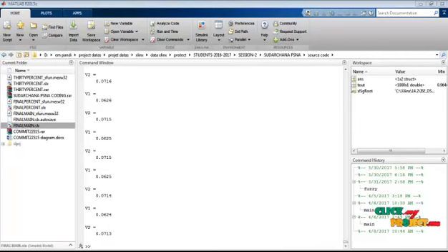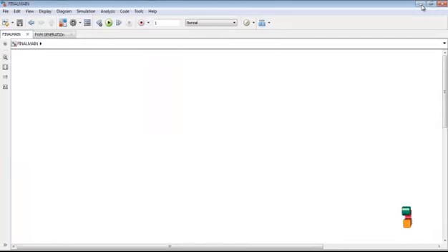Next we see the running process of our product. This proposed implementation is done in the MATLAB simulation environment. First open the MATLAB window and next create a new model file. After creating the new model file, we assign the elements as per the circuit diagram. We arrange the circuit diagram as per the paper. After that we connect the circuits and give the parameters for our requirements. After circuit connection we click the run icon. After clicking that, the output waveforms are shown in the corresponding connected scopes.